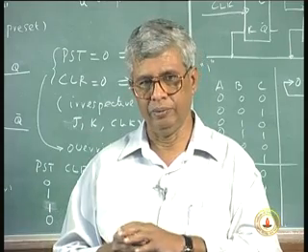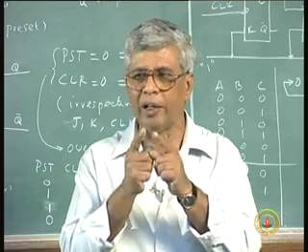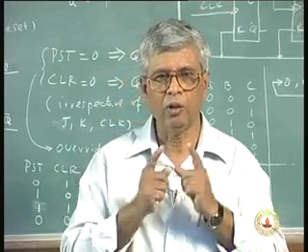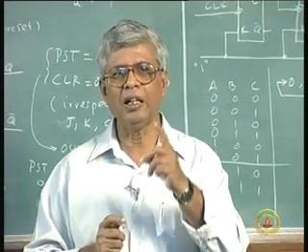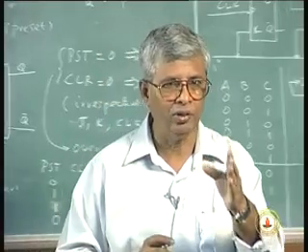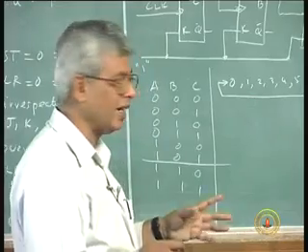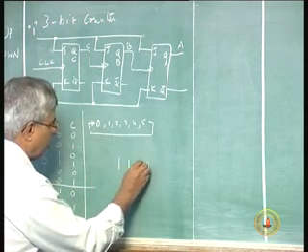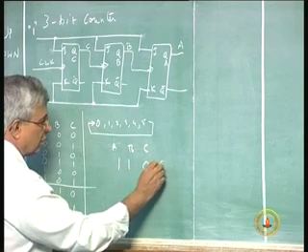If you neglect that, the other alternative is for me to have the clock count 5 only for a very narrow period, which is not correct. I do not want that. I want a full clock period for 5 also. So, actually, if you want to terminate at count 5, you clear it as soon as 6 is reached. So, how do you do that? I detect state 6 and use the state 6 to clear the flip flops. So, state 6 is given by 110. This is count 6.